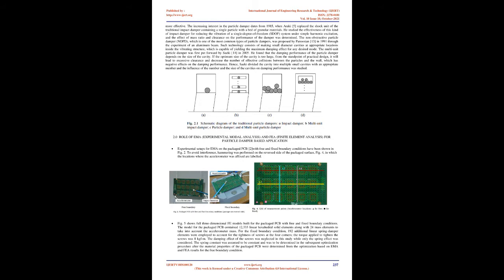2.0 Role of EMA, Experimental Modal Analysis, and FEA, Finite Element Analysis [4], in particle damper-based application. Experimental setups for EMA on the packaged PCB [2] with free and fixed boundary conditions have been shown in Fig 2. To avoid interference, hammering was performed on the reverse side of the packaged surface, Fig 4, in which the locations where the accelerometer was affixed are labeled.